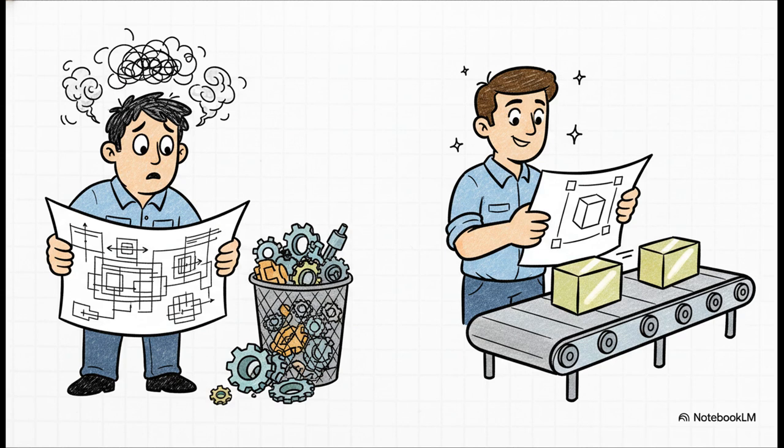It absolutely prevents operators and inspectors from having to do on-the-fly math. In high-volume production, where thousands of parts are churning out every single hour, even a tiny mental math slip-up can lead to an entire batch of wasted parts, which we call scrap. Limit dimensioning is a completely foolproof way to communicate exactly what is acceptable.